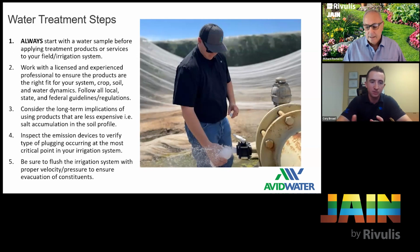And then inspect those emission devices to verify the type of plugging occurring and really where this is happening. What's the critical point in your irrigation system? Because sometimes if the plugging is, I'll say, sediment, which we'll get into, it's going to be hard to deal with. If it's completely plugged in the emitter and there's no way to even get chemistry into it to clean it out, that kind of defeats the purpose potentially. And then of course, be sure to flush your irrigation system with the proper velocity and pressure to get those constituents out. We'll go through some of that in more detail.